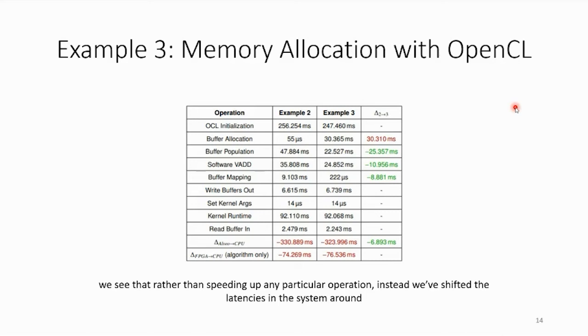Another thing: remember that for data transfer you use the DMA engine from the FPGA, and the DMA engine in the FPGA is a very simple DMA engine. It does not handle all the byte-alignment issues. So the application program has to make sure all the buffers allocated are 4K aligned.